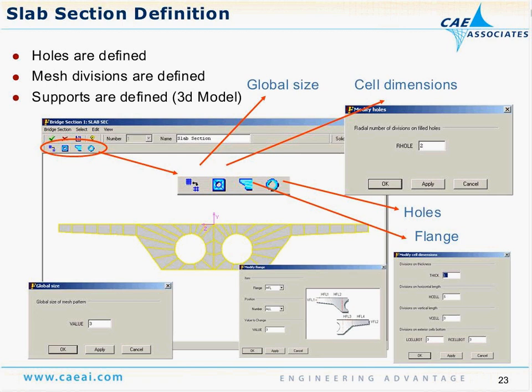And again, each of these cells allow you to define, there's a straightforward description. Also, the sections have an element size for meshing. The meshing will be used to determine, if it's a beam model, where the integration points will be defined for defining the integration of the beam section. If it is a 3D solid model, that's explicitly what the final mesh will look like when you extrude the model.